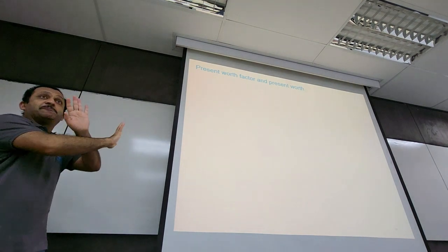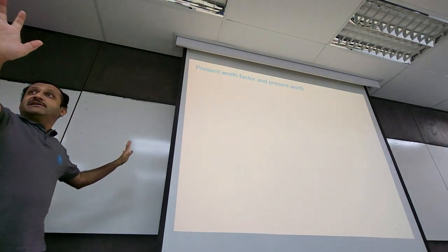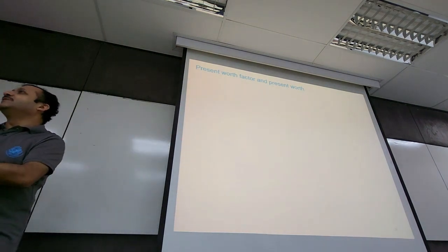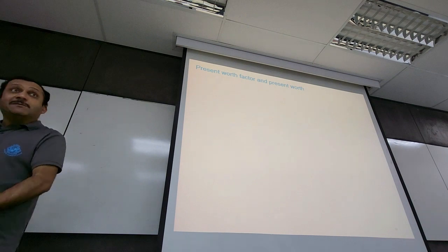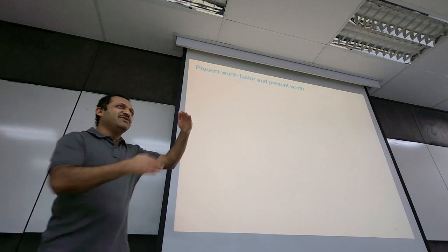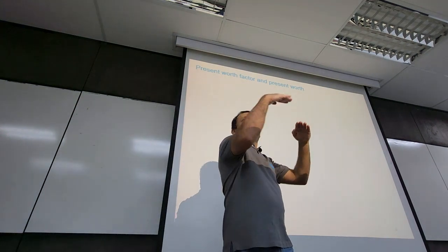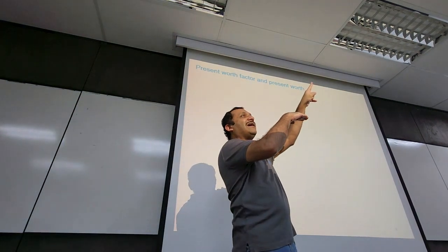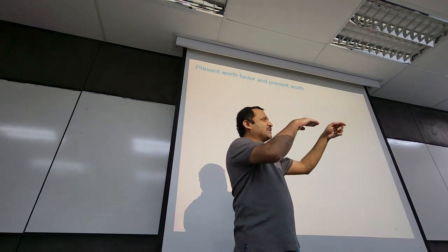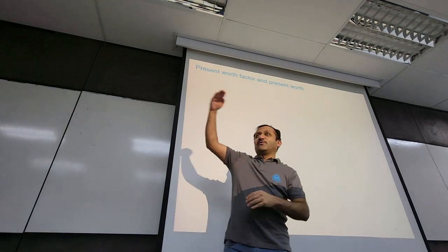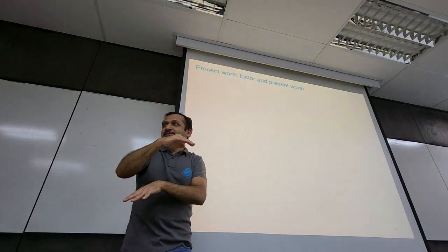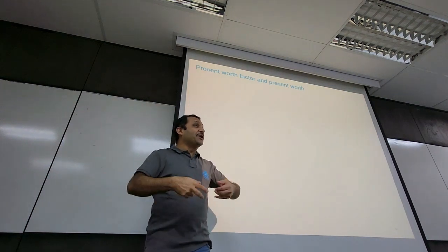And if you have plenty of windows on the north, in winter time it's brilliant because we get a lot of sunlight and we need less heating inside. But in summertime, it can get very hot with all that window. So then we need some eaves on the window, because the sun is quite high in the summer, whereas in the winter right now it's close to the horizon. So if we put eaves on the top of the window, that stops the sunlight directly entering into the room. Things like those. So those are energy saving measures for heating and cooling.